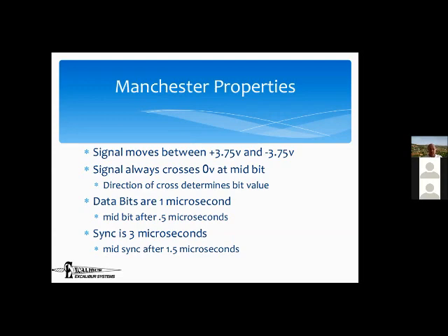Every data bit is 1 microsecond, and a parity bit is also a microsecond. Parity bit is not technically a data bit because it's there just to show that the data is correct, but it doesn't really contain useful information to the user. In fact, the user doesn't even see it. The user will get a status telling it whether the parity was correct or not.